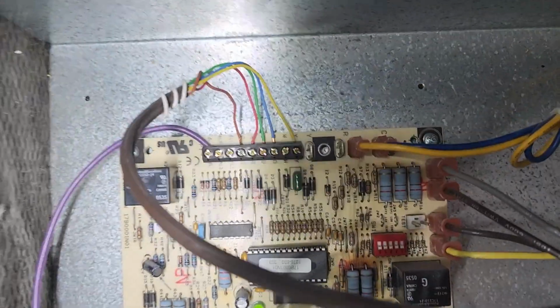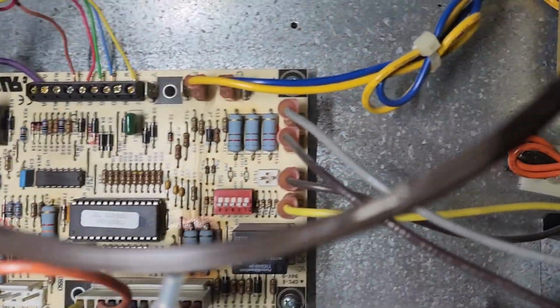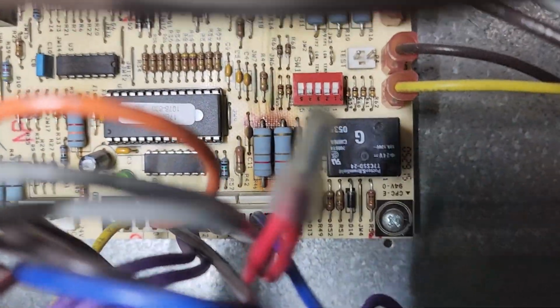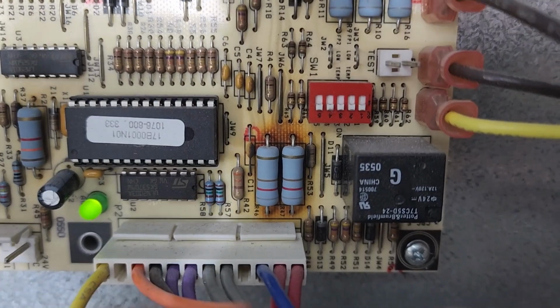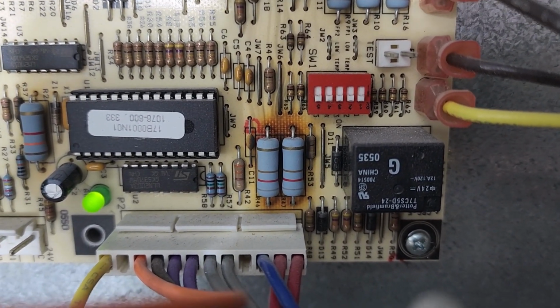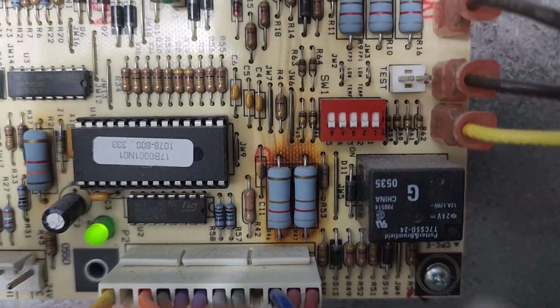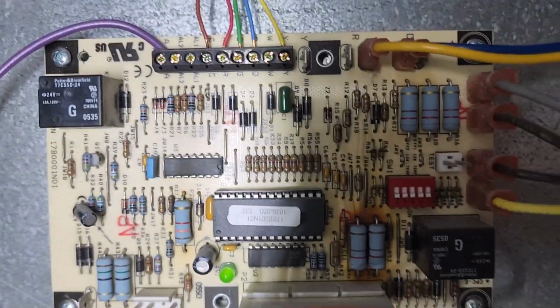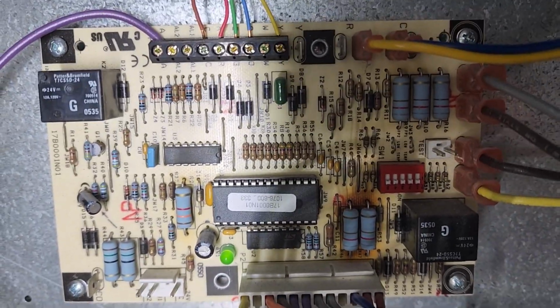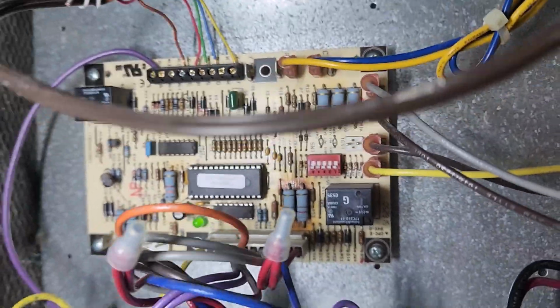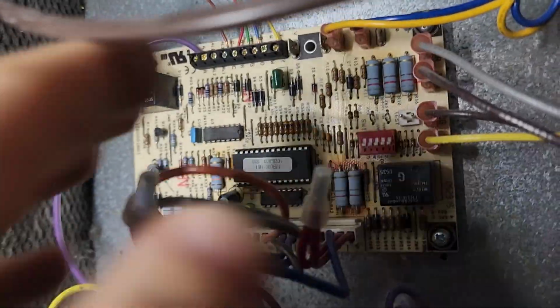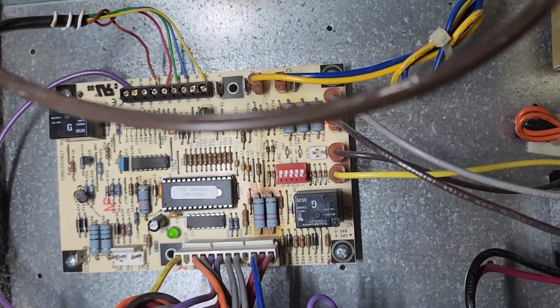All right, so I did a quick little clean, and also reseated some of these connectors here, and turned the breaker back on. Now I also put a flashlight, and one thing, now this is not necessarily the problem, but I do see that these resistors look like they've definitely gotten a little hotter than they should, because we should not be seeing those burn marks on the board. Now we also do see two relays on the board, so very likely one of those is going to be triggering the fan. So again, just not having any experience with this type of system, but using logic and reasoning, we are going to continue our diagnosis.